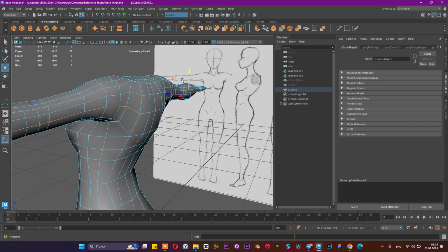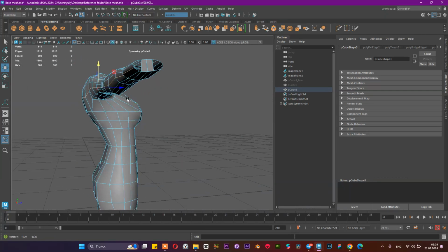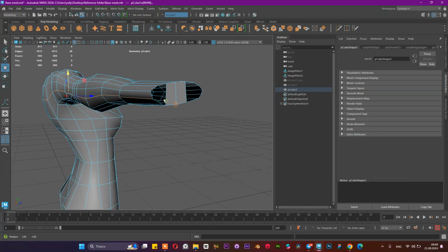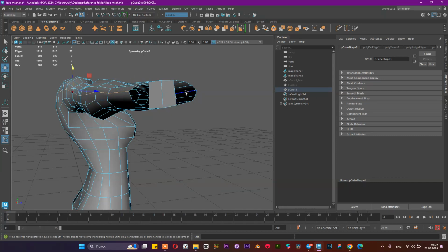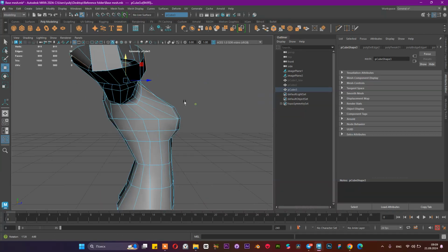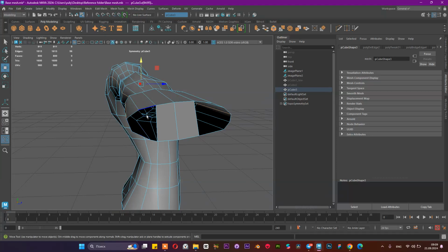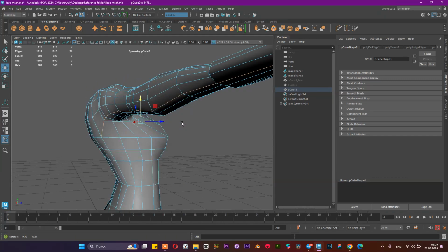For example, if I just move without slide, it moves differently, ruining our soft shape. And if you press Shift, Control, and slide it a little bit, now you can see it calculates in-between positions of this shape, and now it's in a better position. Now we have one, two. These edges will be our central line, and here we have the right amount of edges, I hope. No, this one I think is also fine.